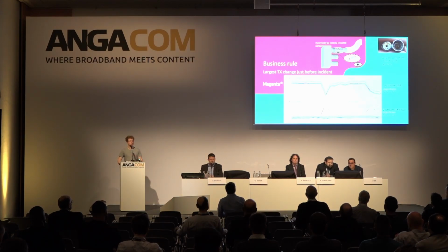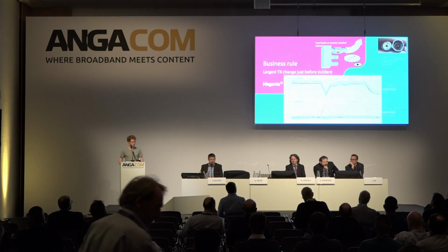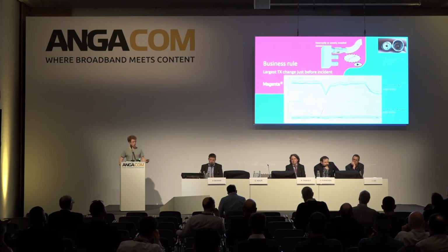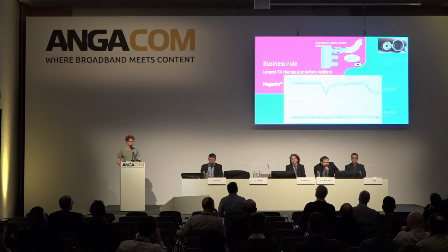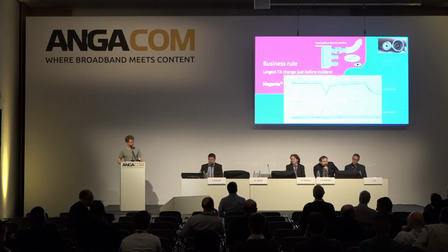So we started simple with a baseline model. This is the term we would use in data science. Perhaps more from the broadband perspective, we're using the business experience of the operations department. What you can see here on the screen is a screenshot from the monitoring tool for a specific, very easy to recognize condition of the high noise problem. We observe that the signal to noise ratio is drastically dropping when an incident is going on in the network, and we can observe that the corresponding TX values of the specific offending modem are increasing. There's a correlation between a specific incident and the root cause. This looks really clear in this case, and it works in some cases. This serves as a baseline business rule already quite well and much better than the previous process.